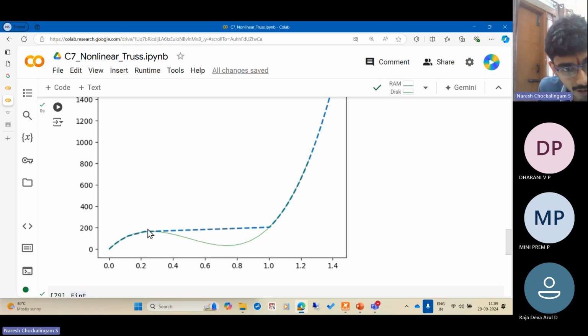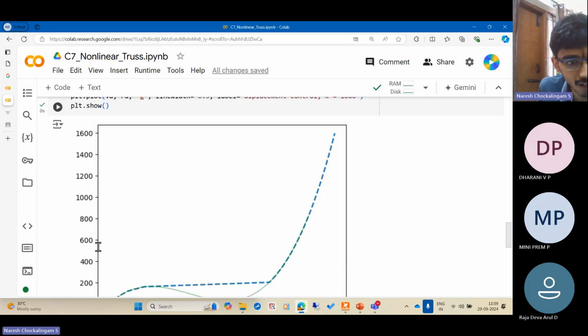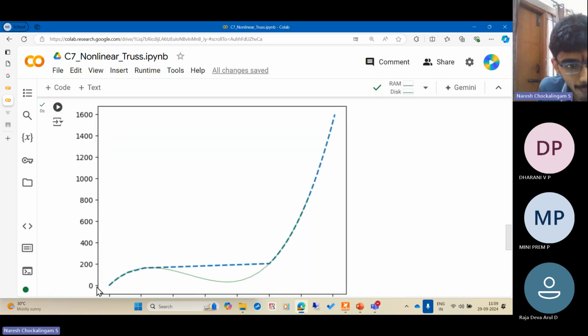But we are not decreasing the force. So from here, it is trying to draw a tangent, and the tangent is meeting only here. Initially, I think the fourth step is 41. So it's like initially 0, then 41, 82, 124, and then we are going to 166. After that, as you exceed that point, it is exceeding the maximum force in this locality. So that force can be achieved only here. So it jumps. This is snap through. This is what I said.